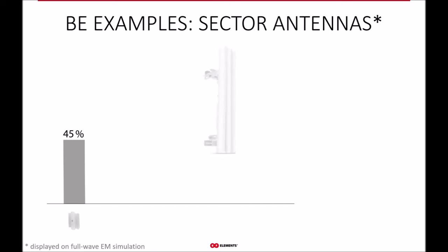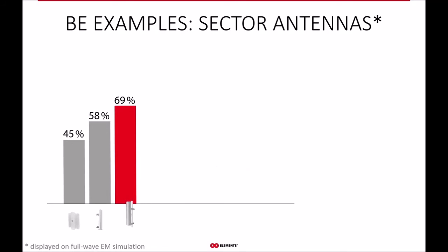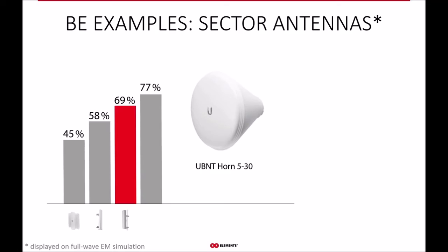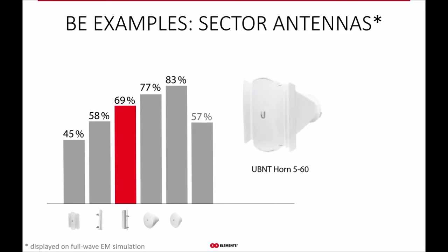The vast majority of antennas used for sectorial coverage in WISP networks are either patch arrays or horns. So reflecting the issues the patch arrays have with the side lobes, meaning their size and the frequency dependence, the beam efficiency of patch arrays is around 60%, depending on the manufacturing and design quality. So now you can directly compare how many side lobes patch arrays and horns have.